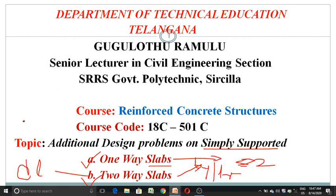After obtaining the factored load, for a one-way slab we have to calculate the maximum bending moment. When designing a one-way slab, we consider a 1 meter width, like a beam. As we are designing a simply supported slab subjected to UDL throughout, the maximum bending moment will be WL square by 8. Like that we can calculate the maximum bending moment for a one-way simply supported slab.